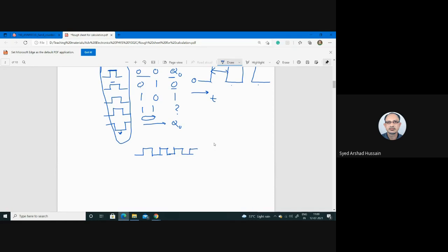So normally up to now we know that as soon as you go on changing inputs, if you change in this region within this time, then the output will change, or if you change in this region the output will change, or if you change in this region the output will not change. But there is a modification: no, I don't want this duration. I want that only when the clock pulse changes from 0 to high, during this transition from 0 to 1, the output should change. In that case, this is called positive edge-triggered flip-flop.